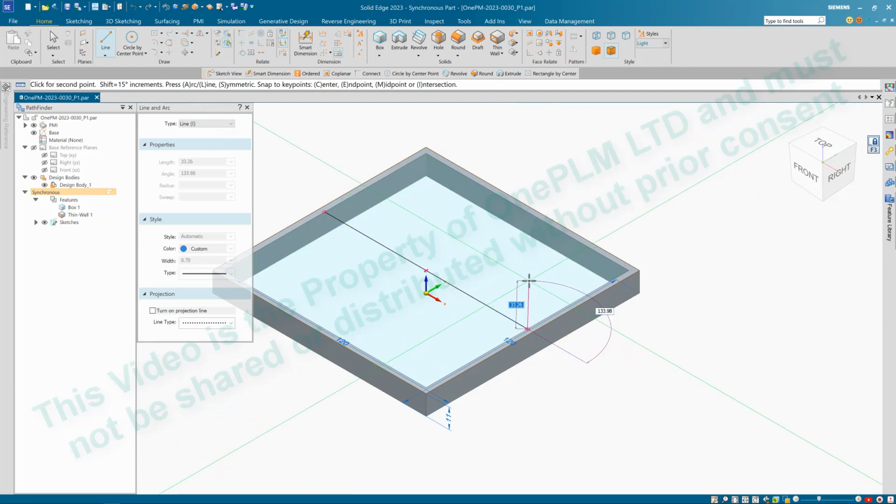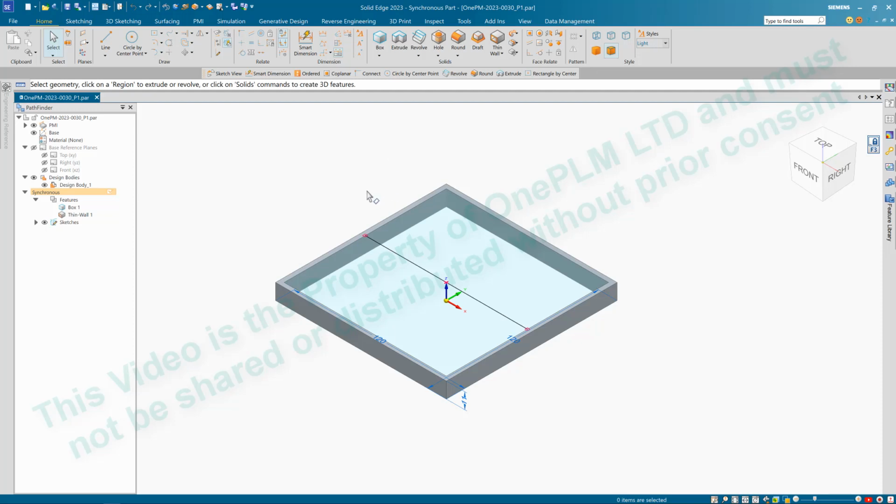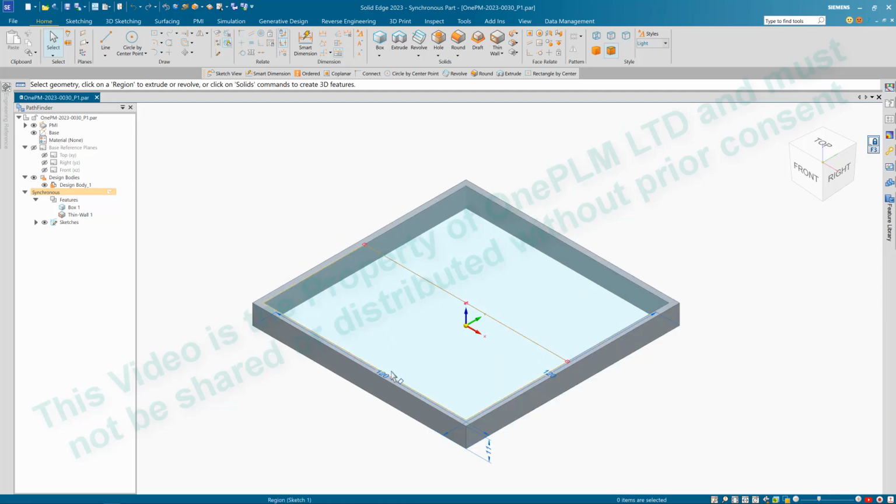Once we finish that line, if we right click, that then cancels the line on there. We can then go back to select, or if we press the escape key, that is our cancel button in that instance. Be aware that some commands do not escape out on purpose, to make sure we don't accidentally escape out. So some of them you do have to physically go to select.